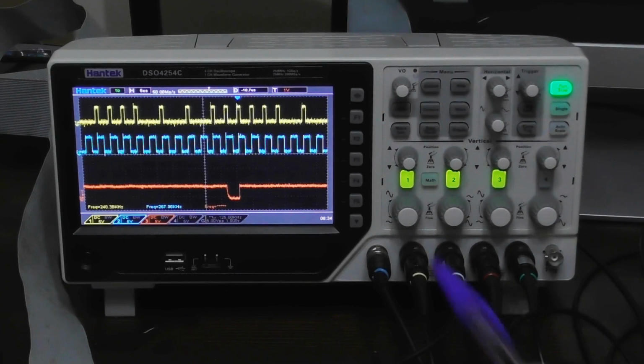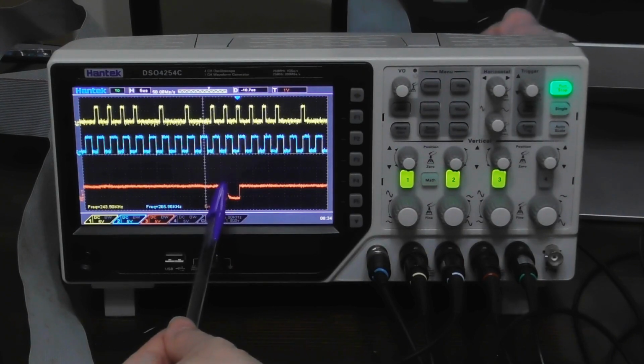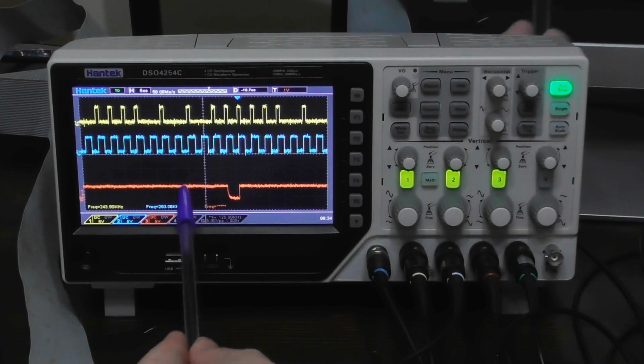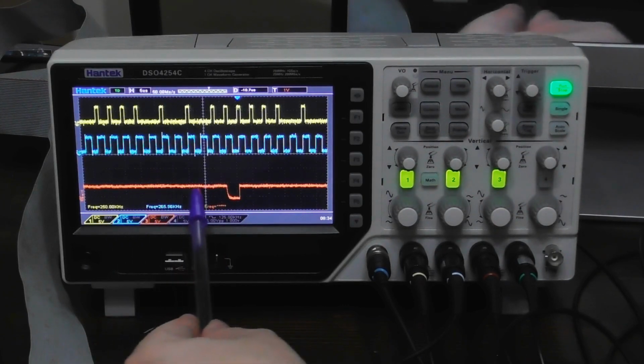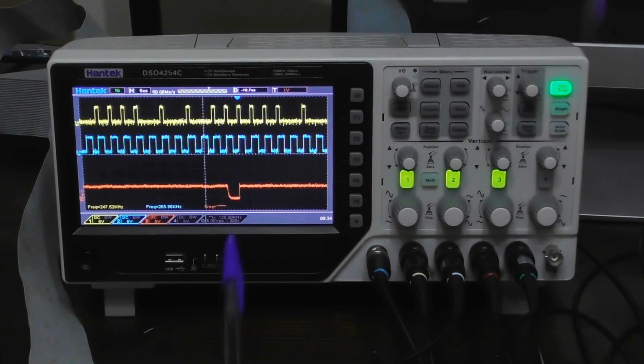So you can see with the changes that I've made to the circuit there, this is now working really well. I've got my little notch down here. There's a slight curve to the falling edge of this now because I stuck a little capacitor in, and that was to get rid of some of the glitches that I was seeing on the rest of the line there. So it kind of smooths that signal out a bit. That's only there for the oscilloscope to be able to trigger on it reliably, so I'm not going to leave that in the circuit when I have say the Arduino hooked up.